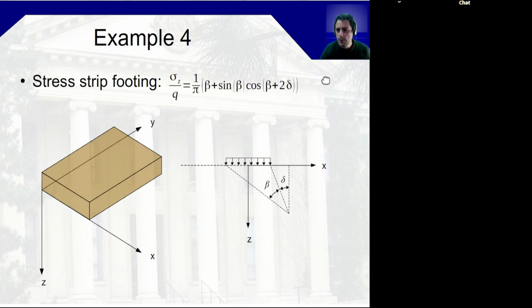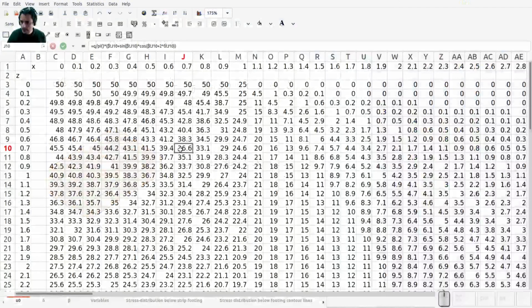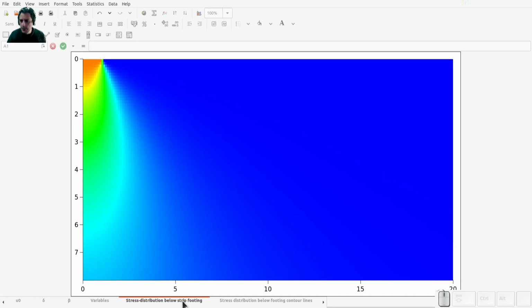We had used this geometry, and under a strip footing, you could use this basic geometry here to estimate the stress. It obviously assumes an elastic medium, but this is all part of Boussinesq theory. So last time, I think that's what we had worked on, correct? And we had generated this spreadsheet. And based on that spreadsheet, we were able to look.